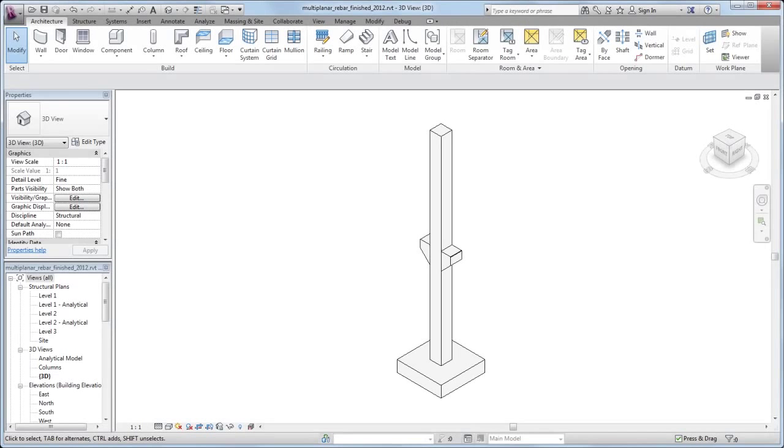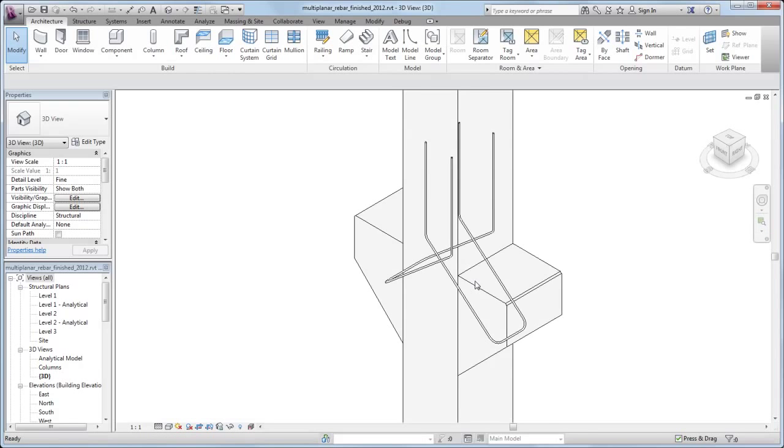In Revit, you typically reinforce concrete elements such as slabs, columns, and beams by placing rebar on a single plane within the element. You can place instances of planar rebar individually, or you can place sets of rebar, where an instance is repeated based on the cover extents of the element. Sometimes, however, your design may require rebar that is bent into multiple planes.